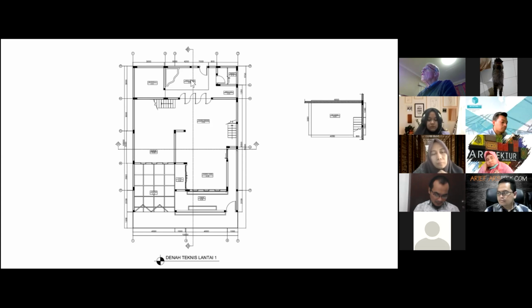And so there will be this torsional eccentricity, and so the building will twist. It'll have huge twisting due to torsion. And so there'll be very severe damage, probably collapse at this end of the building. So that is the problem that I see with this building in terms of resisting earthquake. I'm going to pause and see if you have any questions, and then I'm going to give you some solutions that the student could use to improve the design.